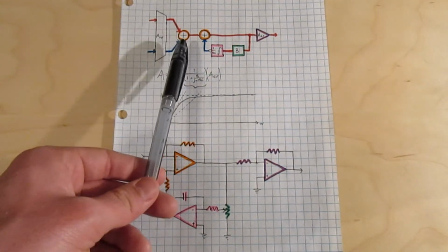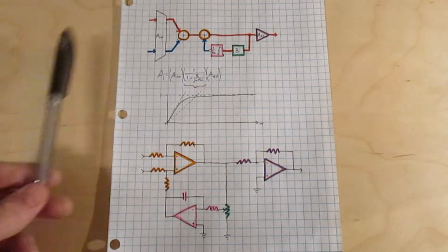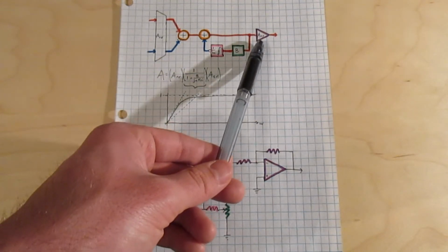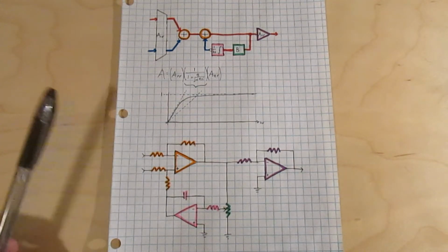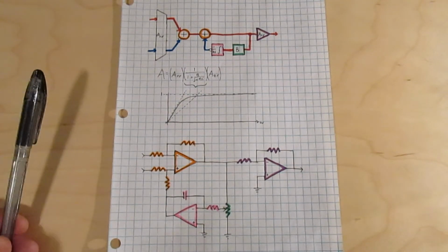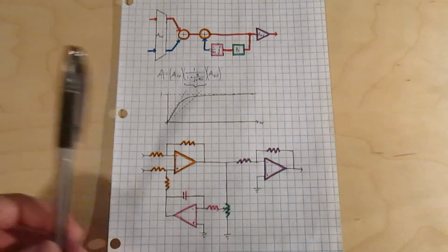This also means that I can't have a gain of larger than 1 at the back end of the in-amp, so I need to compensate for that by putting another amplifier at the back end of everything else. And this is actually the same circuit as the first one I put together that had DC offset tracking, except it has this attenuator and this other amplifier on the back end.